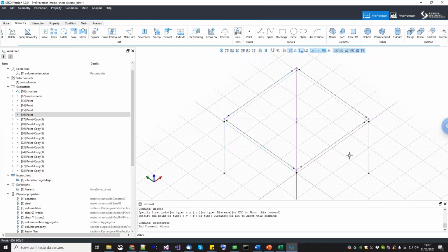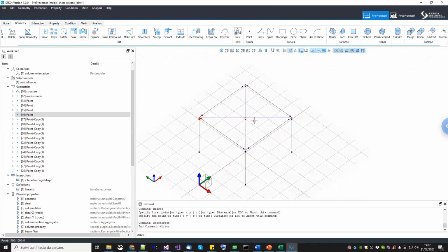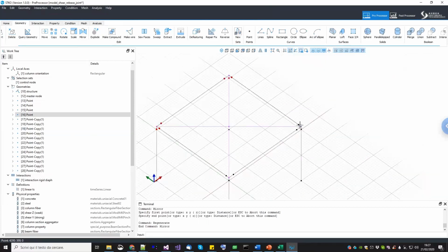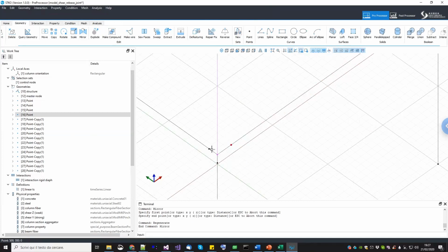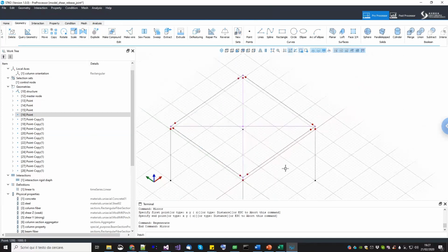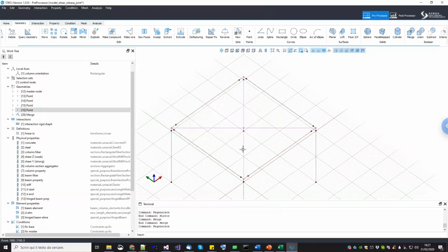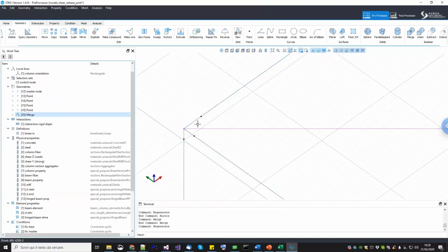Now we need to use them to cut the structure. Okay, so I'm going to select all these points without the corner ones. Okay, only these ones, these extra nodes for the cut. And also this one. And then I also select the entire structure and I click merge. Merge will basically merge them in one single Boolean operation. Okay, perform intersection. Perfect. Now we have our master node, previous master node, our merge geometries, so the previous beams still continuous, but with this cut here. And then we have these 4 points that will be used later on.